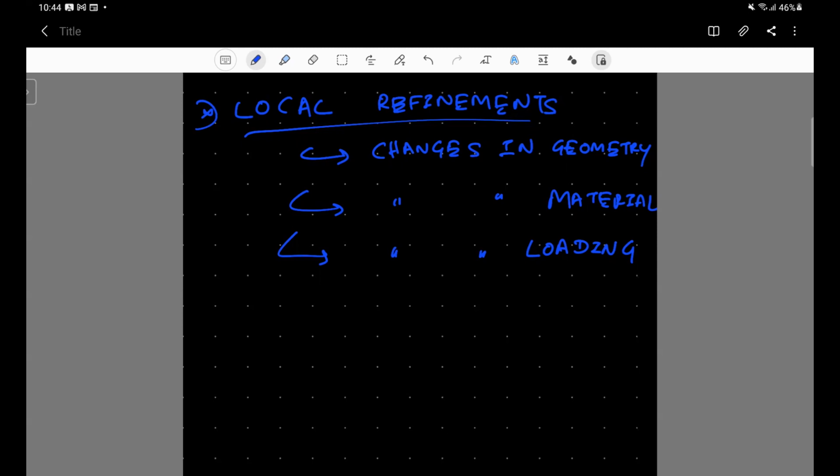It might be the case that your mesh has local stress concentration, so your mesh is invalid in certain locations. So residuals are important. You need to test whether your solutions are converging.